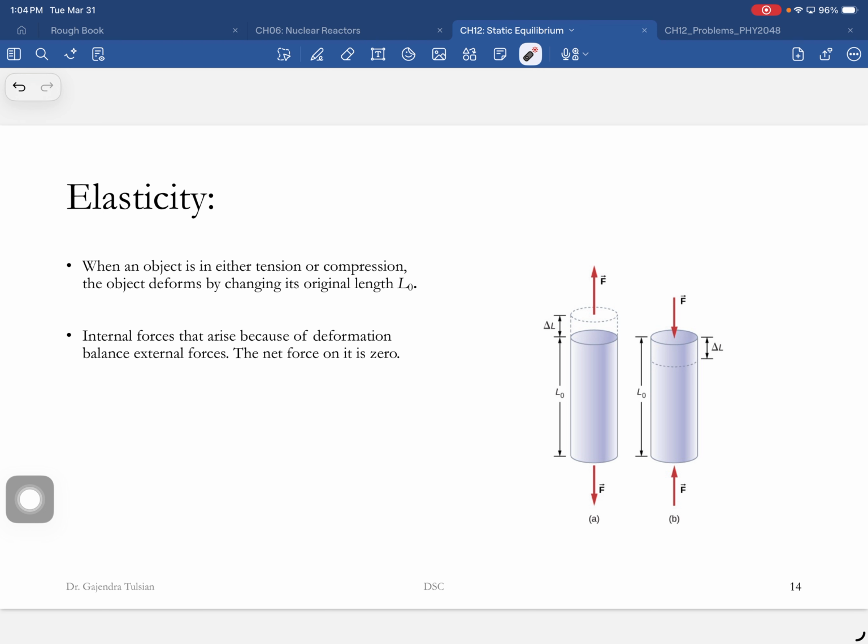All right, so let me see what your intuition is. And again, I wouldn't have been able to guess before I learned this. Okay, so let's say this is a concrete pillar. Let's say I apply 1,000 pounds like this or 1,000 pounds like this. When do you think it'll break? The pull will break? Yeah, that's correct. So it is weaker under tensile forces and stronger under compressive forces.